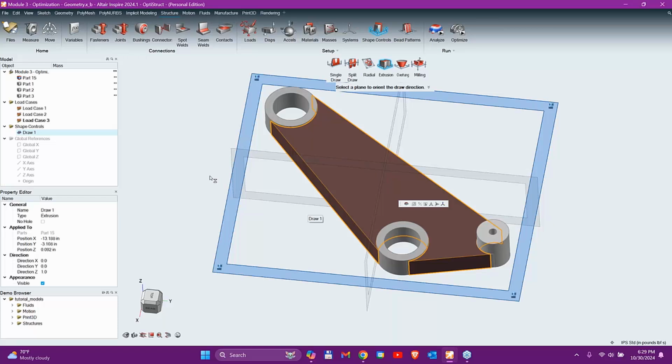So there is a maximum angle at which you can print the next layer up. And utilizing this will guarantee that your part maintains specific overhang angles, which means that you don't have to create supports for it. And then finally, milling allows you to determine 5-axis milling constraints to guarantee that your part is millable on a 5-axis machine.